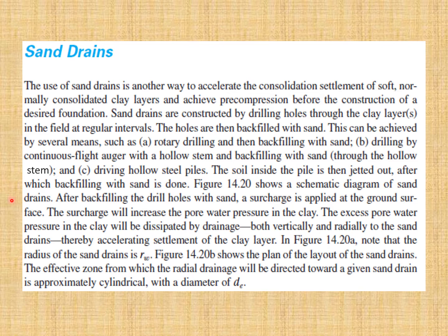After backfilling the drill holes with sand, a surcharge is applied at the ground surface. The surcharge will increase the pore water pressure in the clay. The excess pore water pressure in the clay will be dissipated by drainage, both vertically and radially.